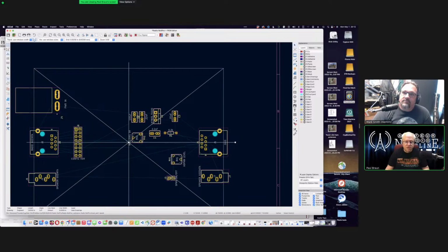Okay, so this should probably move. You think this should be closer to the header? I would probably put it closer to the radio side, yeah. Because it's going to be more powerful, which means you're less likely to pick up noise on the audio side.